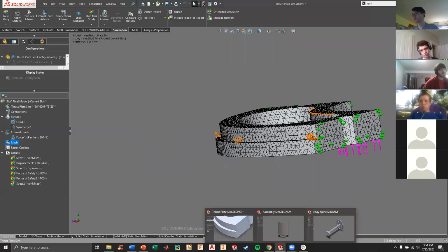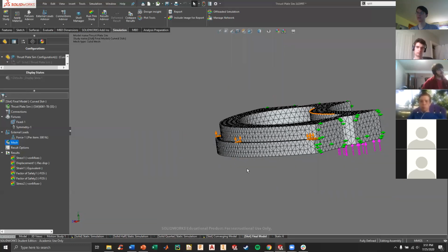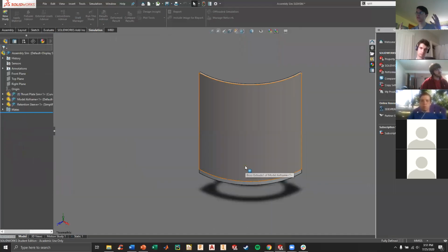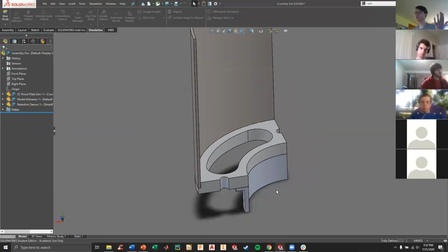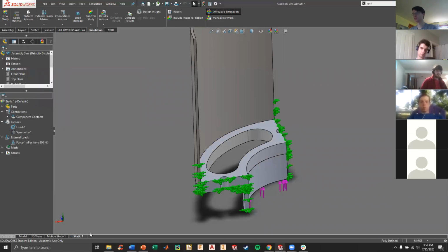A lot easier method to get around it is to go with the idea of fixing your geometry kind of 1 degree outside of the area of interest that you want to study. And that's going to be a great way to get rid of singularities. Not entirely, because we're still going to be using a fixed geometry, so there's going to be some kind of weird interaction singularity there, most likely. But get rid of singularities in the area of interest that you want to look at.